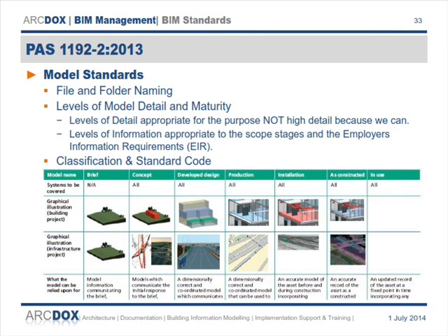PAS 1192 doesn't define levels of detail. It defines levels of model definition. But you will hear as you go through projects people referring to LOD 100 to LOD 500. Okay, that's an American standard. It's not something that the UK go into, but it is being required on projects. We've seen it on projects where they're calling up these levels of detail.